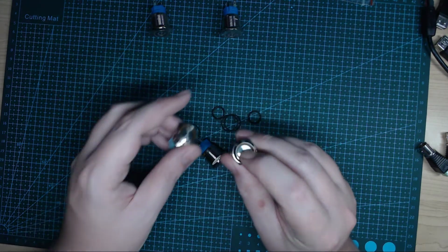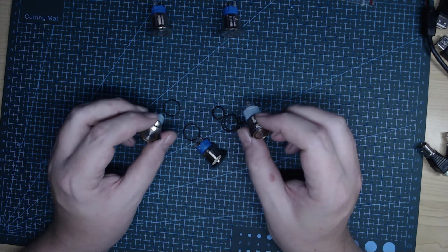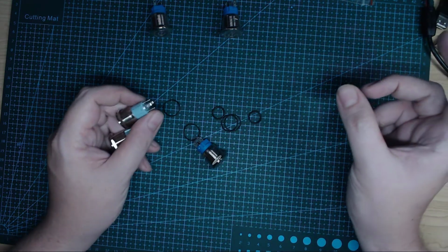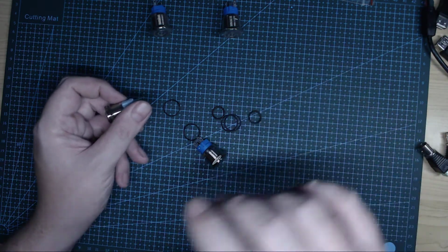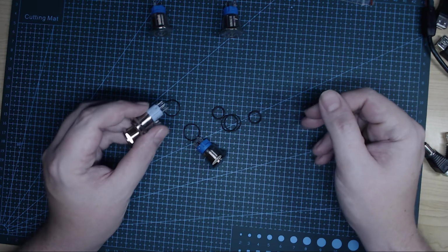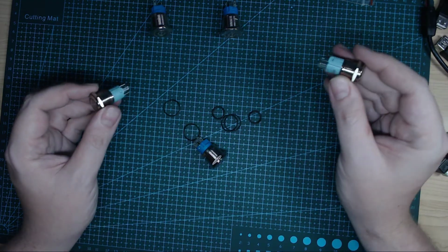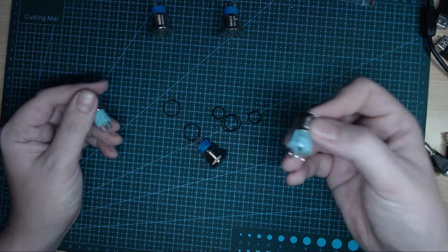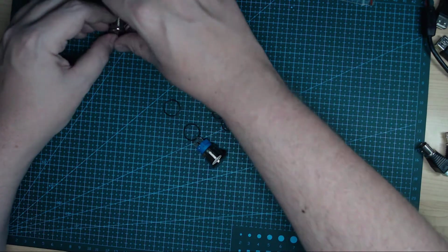And these two orange ones will be for diodes on the output. So I'll have the power supply go through a big chunky diode, or possibly a few in parallel, which will then go to the output pin, which then lets me charge batteries and whatnot with the power supply. But those diodes introduce a voltage drop. So these switches I added in as bypasses. So I'll be able to press the switch on and short out across the diode to remove that voltage drop in cases where I know the diode isn't required. So that's just a little addition for it.